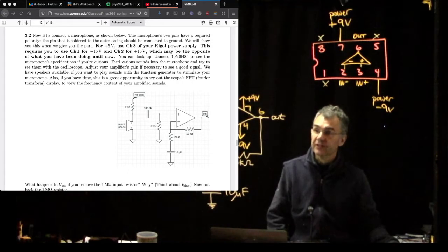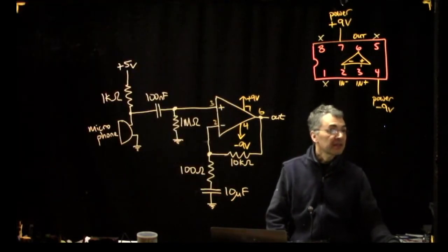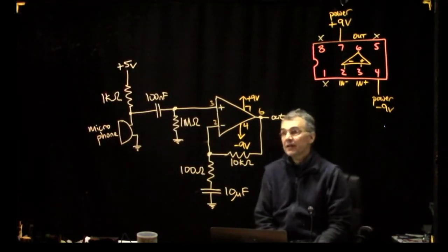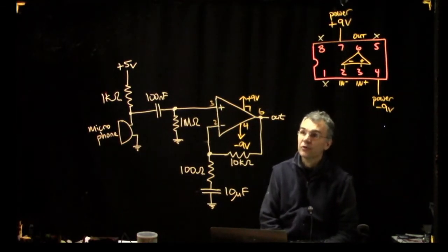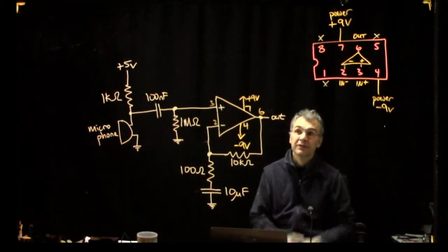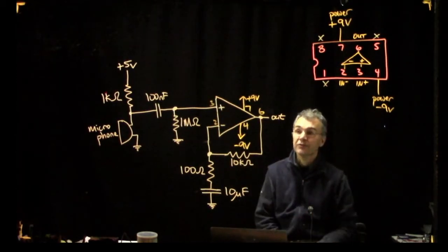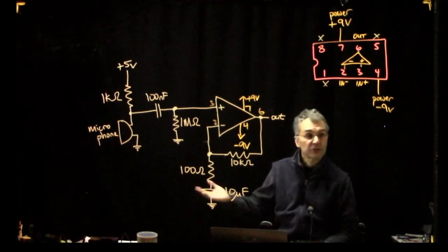And that's a convenient thing to do because all of the op-amp imperfections like I bias and V offset and so on are DC phenomena. They're all constant as a function of time, whereas an audio signal has no DC component.